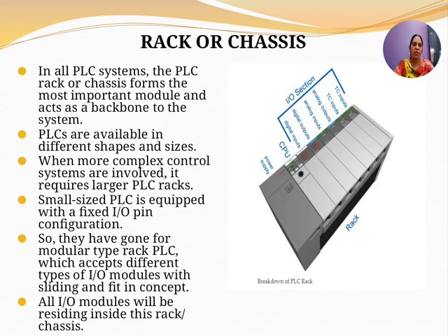You can see in the figure, we have the power supply at the lowest part, then the CPU, central processing unit, then your I/O, input output section. So the rack is holding the entire unit of the PLC. It is like a backbone, like a support. It may be of different sizes and shapes. The modular type of PLCs accept different types of I/O modules, digital inputs and other things, with the sliding and fit-in concept. So this is your rack or the chassis.